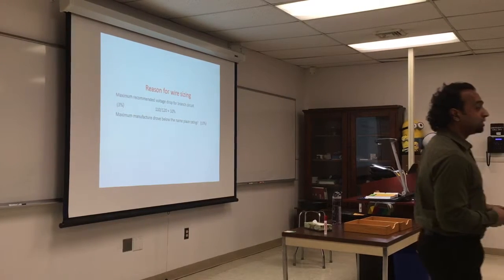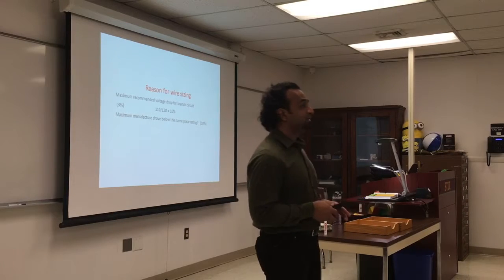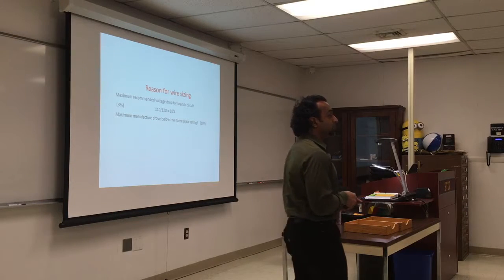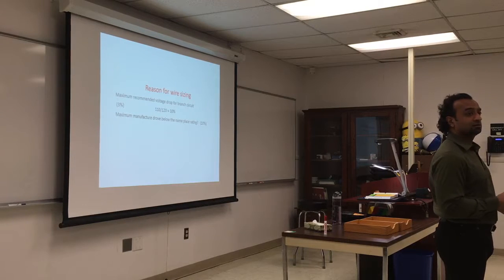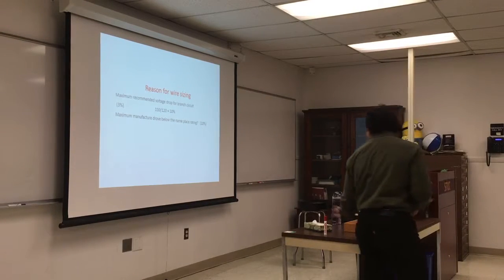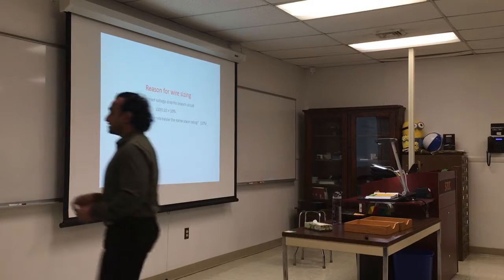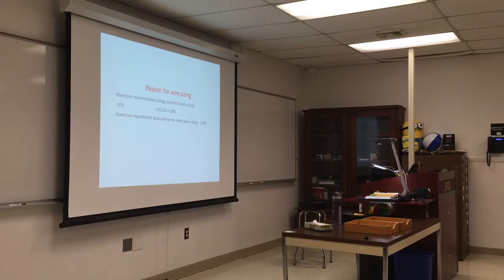Because again, most of this equipment is rated on 14 gauge. So probably you will need to lower the resistance. And how do you lower the resistance? Making the wires bigger? Yeah, you increase the gauge. So we also said that, which one has more resistance between those two?